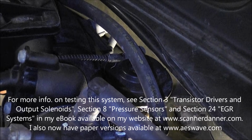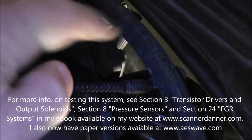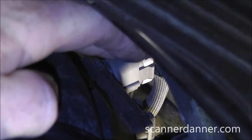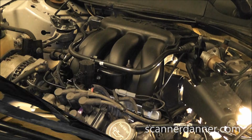Okay, our EGR valve is right underneath this, looks like maybe a PCV hose. So it's just a single vacuum type EGR. And then the DPFE sensor is kind of buried in the back here. That's why I have the light underneath the car. It is actually that guy right there. You see the gray connector going to this box. Very difficult to see the rest of that DPFE sensor. So that one's kind of difficult to get to, but we'll be able to rely on scan data to test that. So I'm going to do the test now.